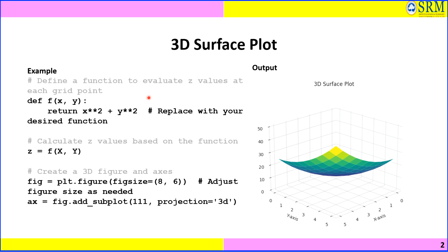After that you can directly write z = x square plus y square, or you can write the expression in a function and store that in z. So for the x, y function, we are creating the expression x square plus y square and storing it in z. Again we have declared all the values x, y, z, where z depends on x and y. After that we have to enable the figure, similar to the previous one.